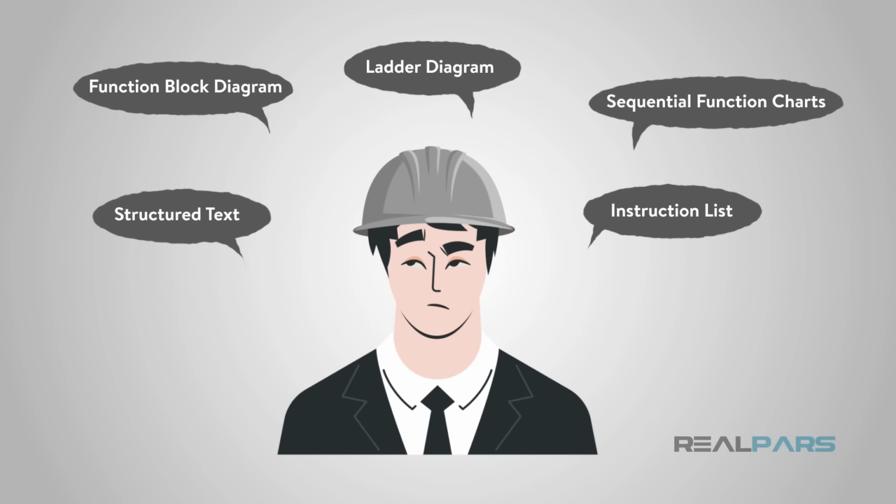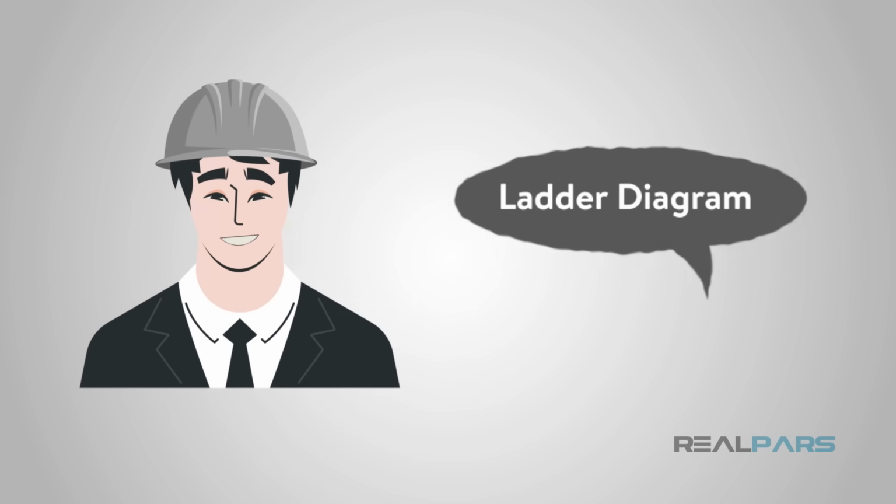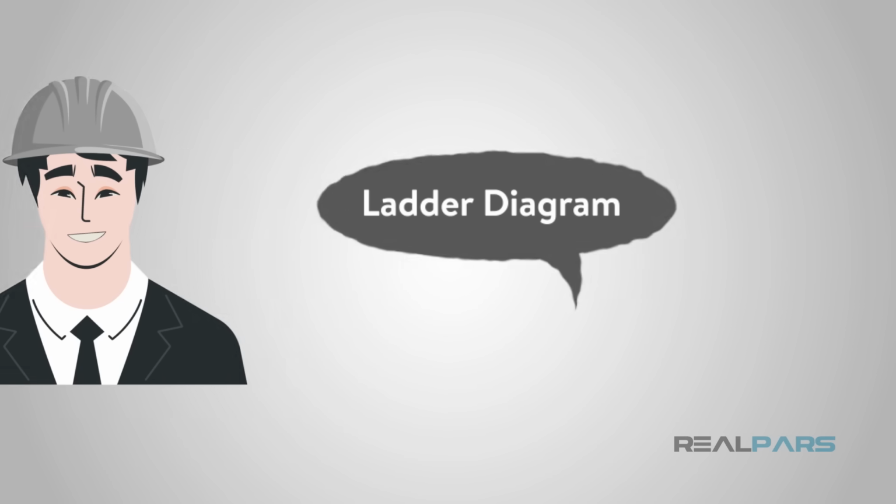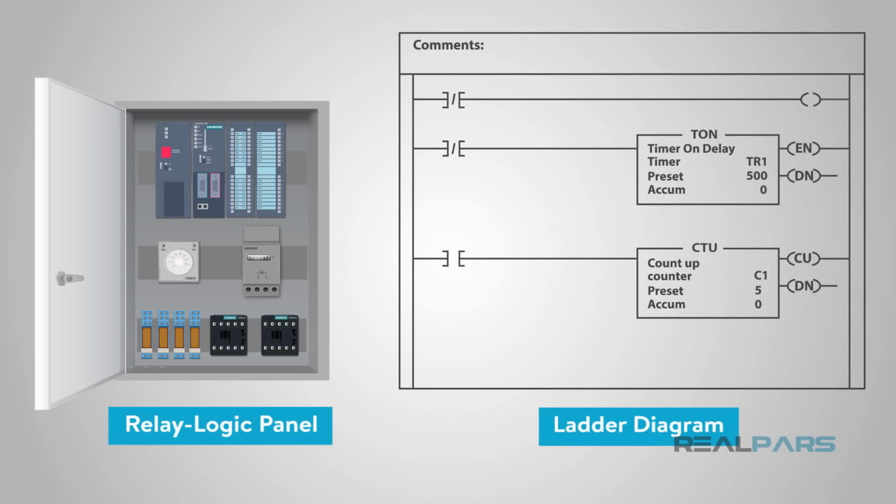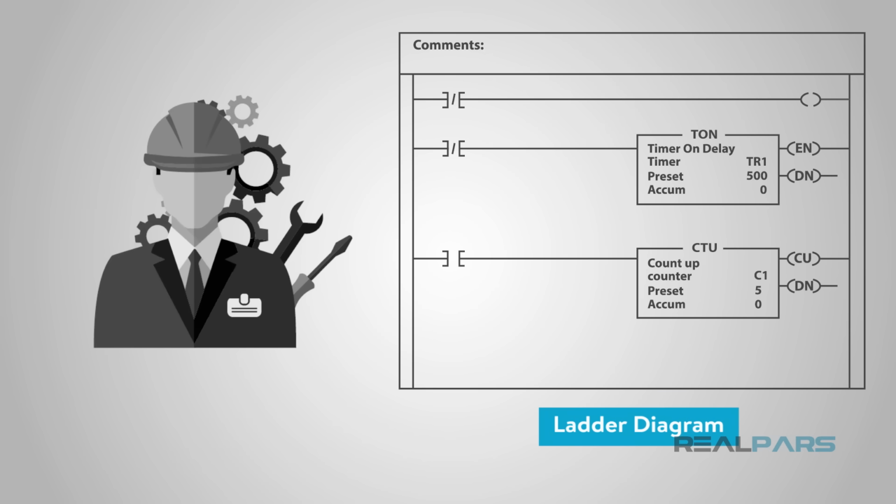So, have you decided which PLC programming language you consider to be the most popular? After reading many reviews and opinions, and with my own experiences, the ladder diagram language is by far the most popular. The main reason for this is that the ladder diagram language naturally followed the technology advancement from a physical relay logic to a digital and logical one. This allowed the engineers and skilled workers to follow and troubleshoot and make that transition.